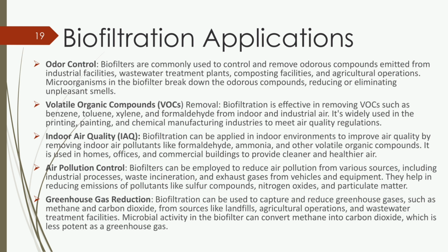Microorganisms in the biofilter break down the odorous compounds, reducing or eliminating unpleasant smells. Volatile organic compound removal. Biofiltration is effective in removing volatile organic compounds such as benzene, toluene, xylene, and formaldehyde from indoor and industrial air. It is widely used in the printing, painting, and chemical manufacturing industries to meet air quality regulations. Indoor air quality.